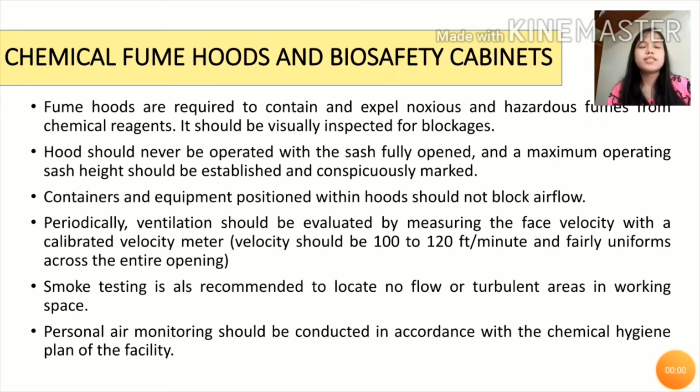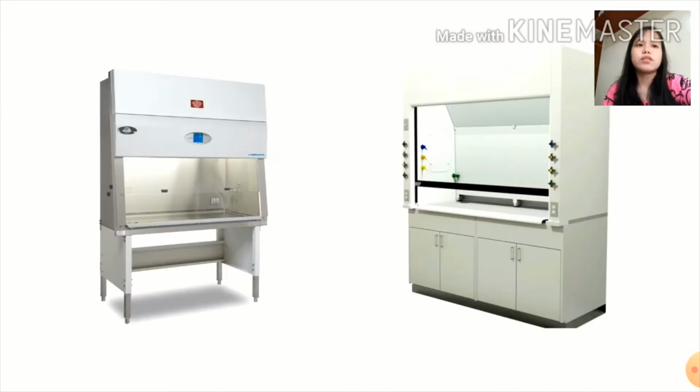Chemical fume hoods and biosafety cabinets. Fume hoods are required to contain and expel noxious and hazardous fumes from chemical reagents. They should be visually inspected for blockages. Smoke testing is also recommended to locate no-flow areas in the working space. Personal air monitoring should be conducted in accordance with the chemical hygiene plan of the facility. So this is how fume hoods look like.